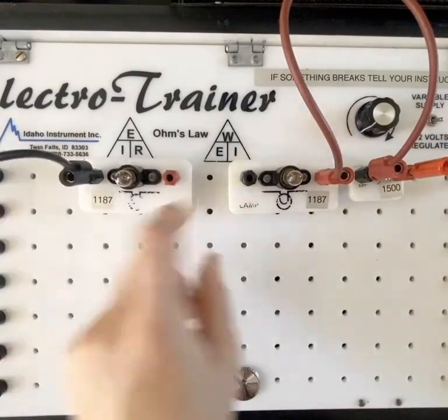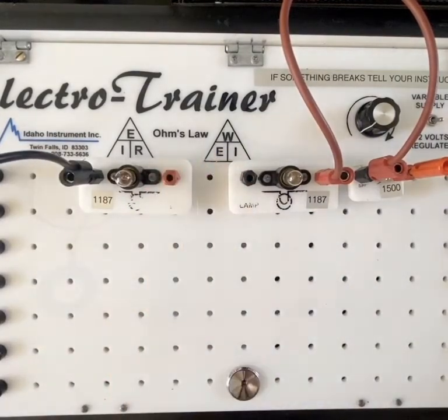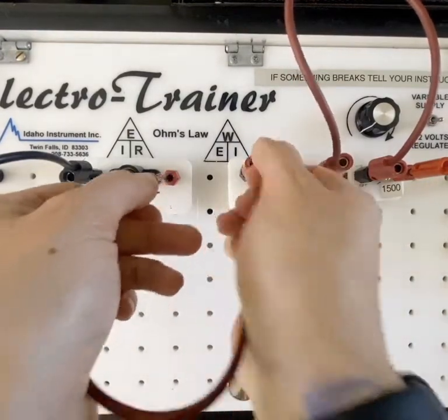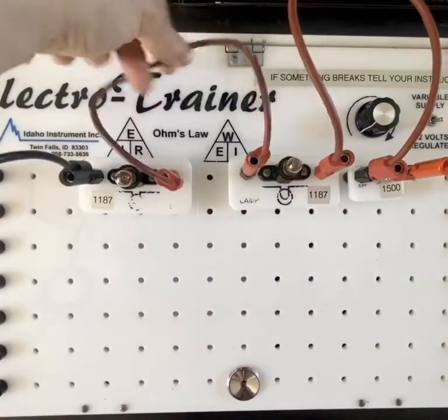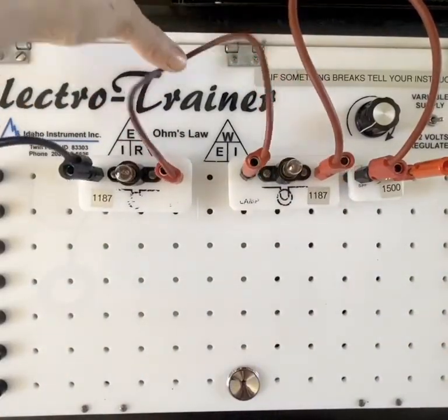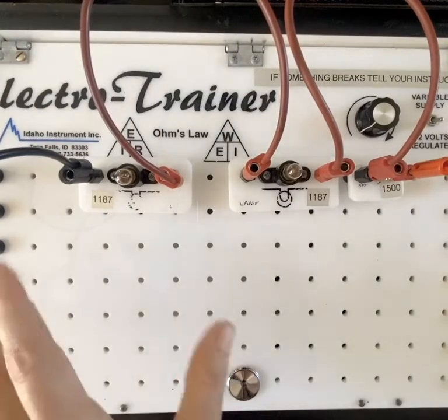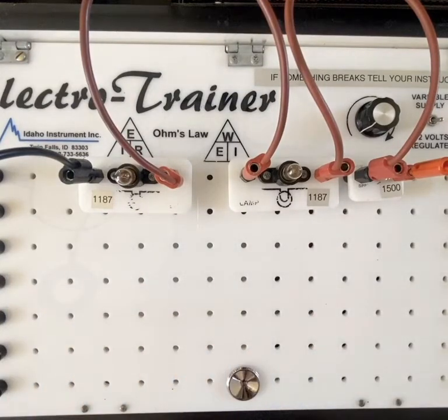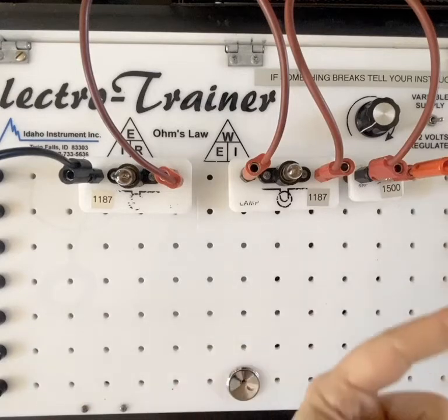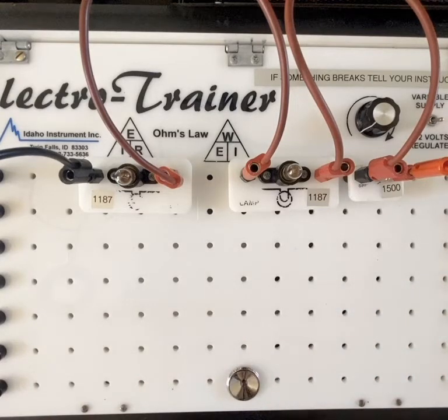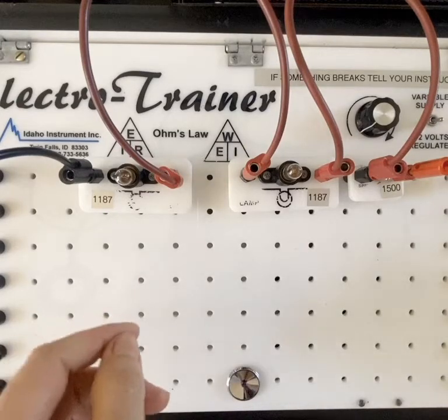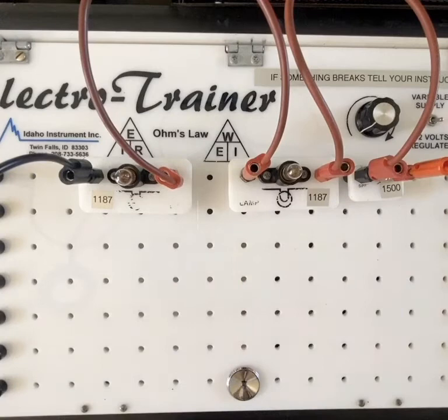But right now, since I have no wire connecting these, my light's not going to turn on. So we'll add one more wire. I can use either color. It really doesn't matter. They are the same inside. The reason I am color coding this for you guys is so you can realize I'm using the red wires to show you where voltage is still going to be, and then my black wires for where no voltage should be. Now, let's see what happens.